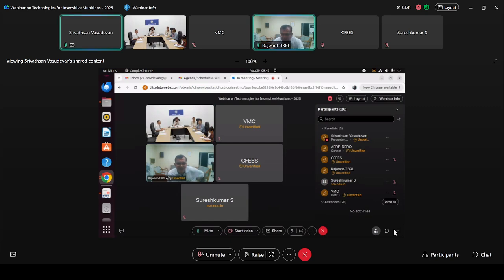Yeah, I want to just add, Professor, that Wi-Fi and Bluetooth technologies are not able to transmit the data at faster speed, and the distances which we are looking for are more than 100 to 200 meters in our experiments. So as suggested by Dr. Indrapal, we should look for a localized storage, maybe around 5 meter or 10 meter away, using conventional cables, and then we can combine that data through an optical link. We can lay one optical fiber line, and we can transmit that data to the server.